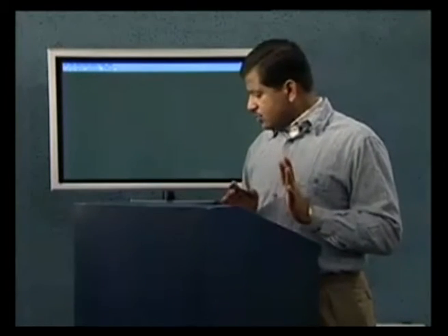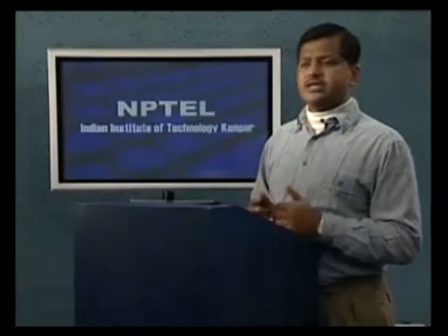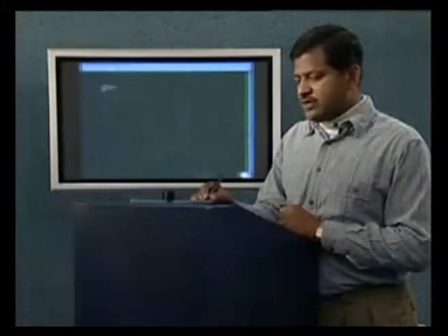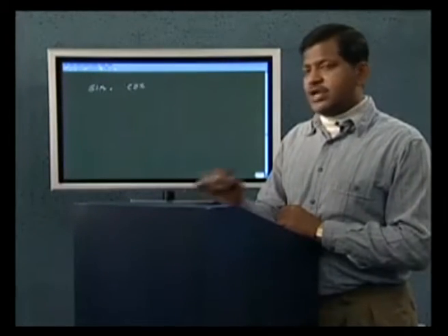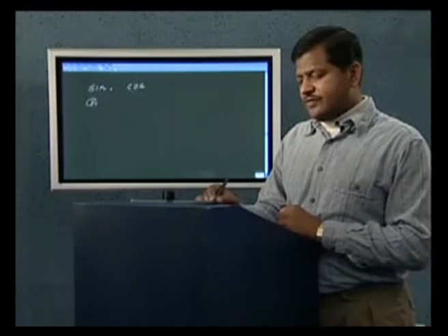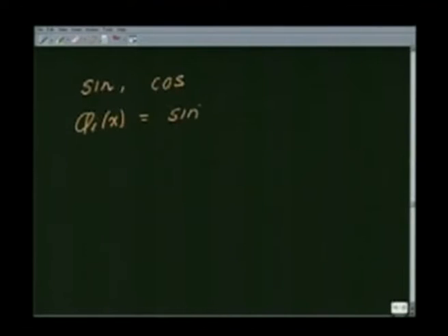So this is how you would construct the Rayleigh-Ritz solution for a variety of problems with different boundary conditions, different load vectors, different material coefficients, using a polynomial approximation. Now nobody tells us that we should use a polynomial approximation. We can also use sine and cosine functions. For example, we could have chosen phi i of x equal to sine n pi x by L.